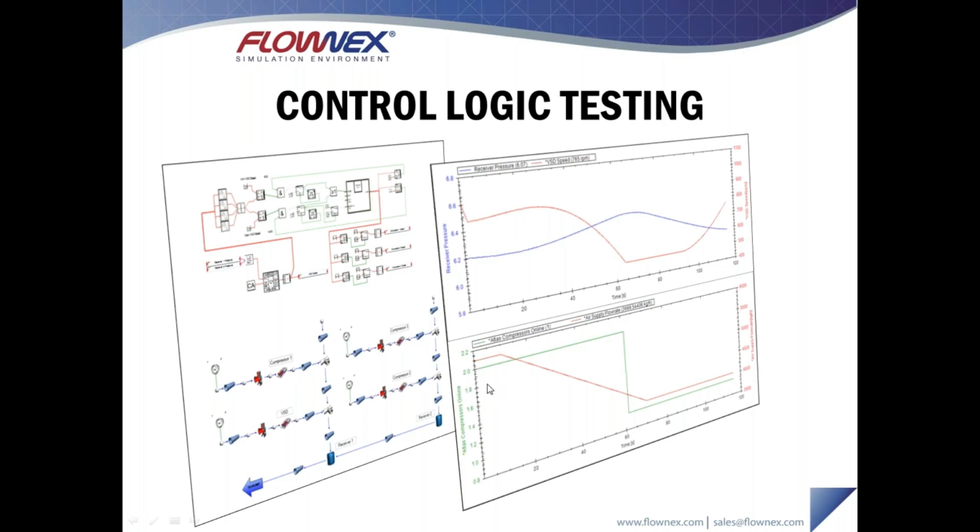In this example, what I have here is a reduction in the air supply flow rate. That's this red line on the bottom graph. We start out at a supply of about 5,500 kilograms per hour of compressed air, and then reduce that slowly down to about 4,000 kilograms per hour. This change is made over about a minute, and as a result, we can see our tank pressure begins to increase. As the tank pressure begins to increase, we see our variable speed drive decreasing because the amount of air required reduces.